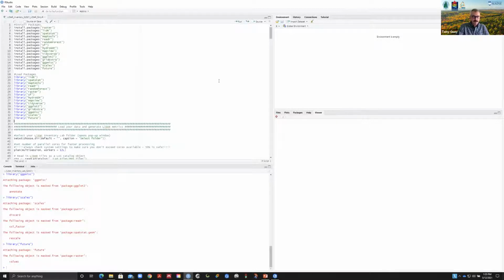It is fairly complex and a bit cumbersome, the workflow involved. But we did receive some feedback from our partners, Seven Islands and the folks at the Land Trust in Rangeley. We used that process, and then they went out and measured the field plots with survey grade GPS, fixed radius plots. We told them where to put the plots based on the structure of the point cloud, and achieved some very good results of the EFI. And I believe that was also using the QL2, the state LiDAR. So I'd mention that also as we're thinking about doing this.